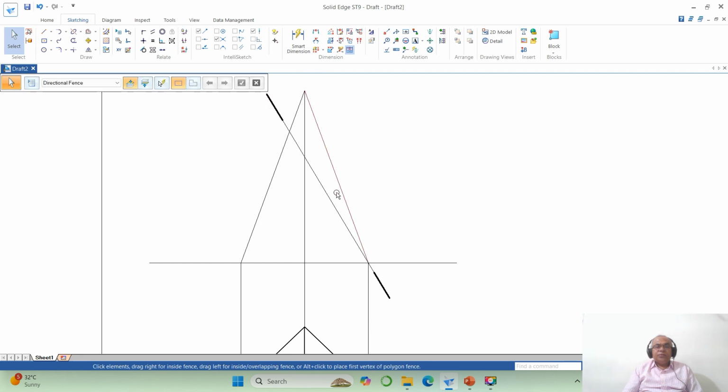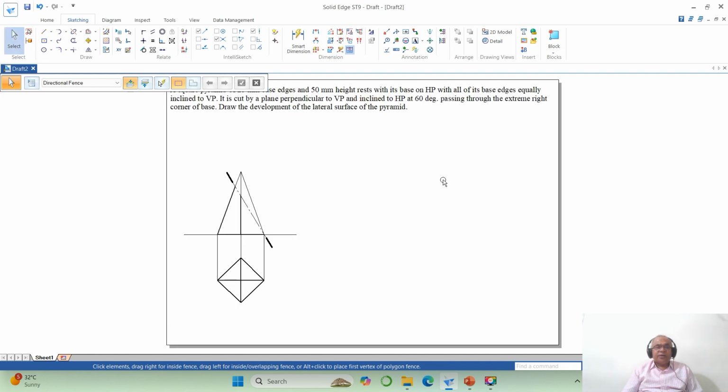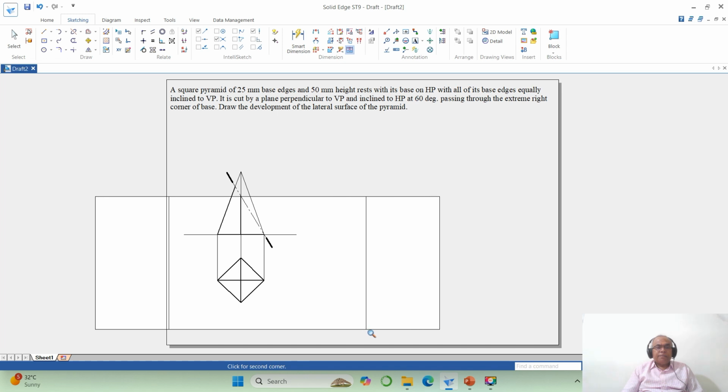Okay, then you select this line and take this as big dash, small dash, like this. Now you go to split this line till here, then you split this line till here. Of course you don't have anything for that, so you select all these three and make this as 0.5. Now once you do that, you have the drawing completed both in the front view as well as in the top view.